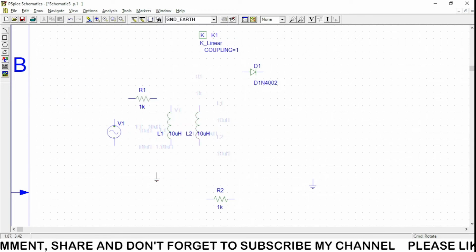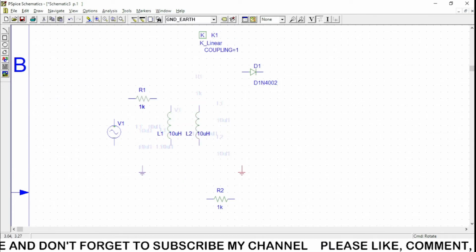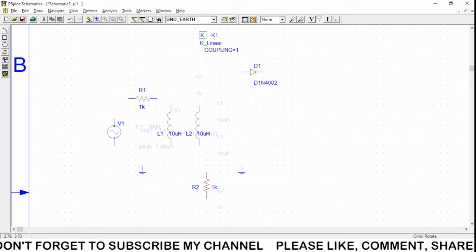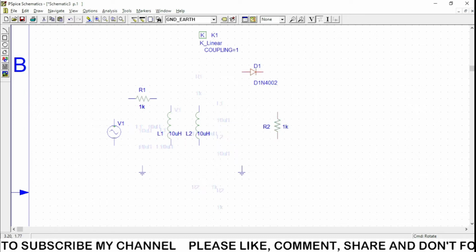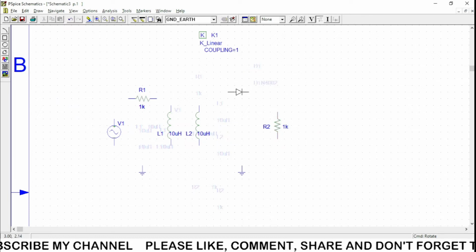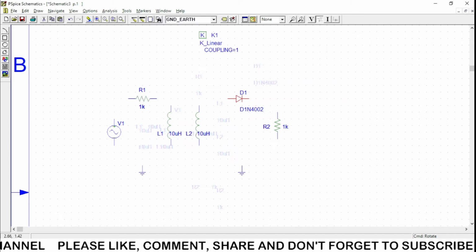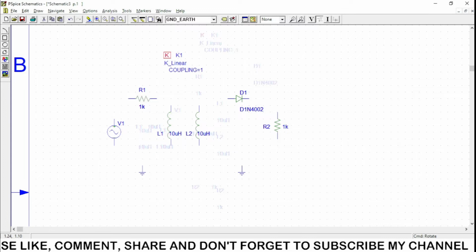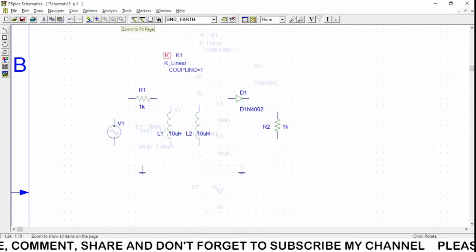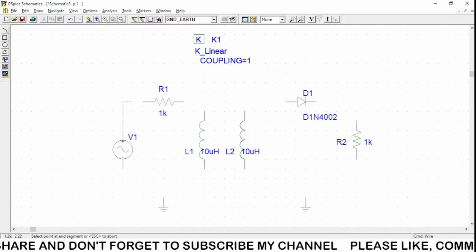The ground terminal is required at this part as well as at this part. Resistance R is needed as a load because we have to see the output at the resistance. Okay, so this is done. We need the K linear part, so I'm going to place it over here to fit to page. Okay, so press Control W to join all these things together.